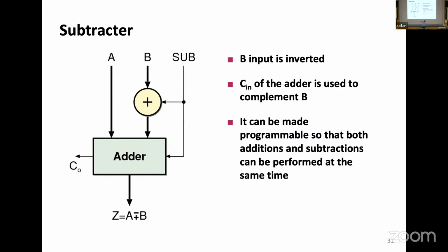And all I had to do is add 1 set of XORs on the path of B and 1 signal. Like, we did 1 adder, but it's solving us multiple problems. Now, the best part is, and I'm not going to go into the details, just trust me when I say this, because it requires a little bit more discussion. If you can subtract 2 numbers and you look at the results, you can already make all the comparisons, right? If A is greater than B.